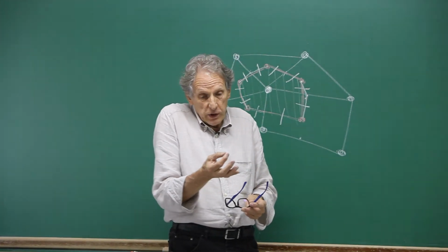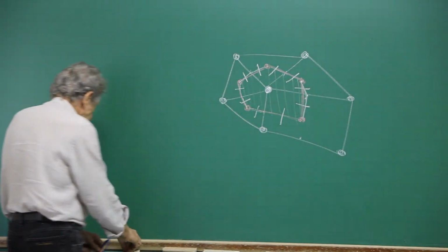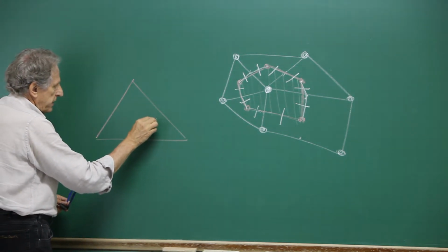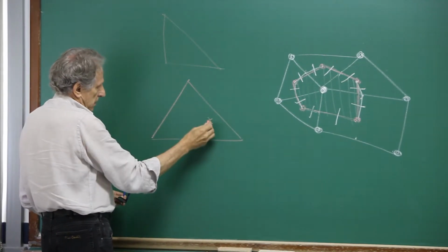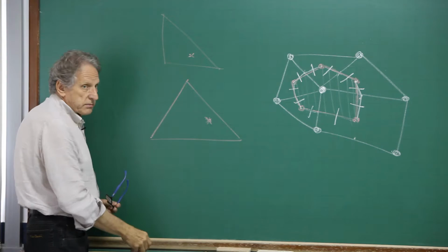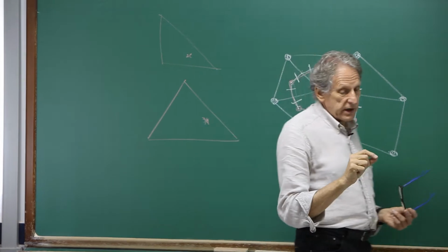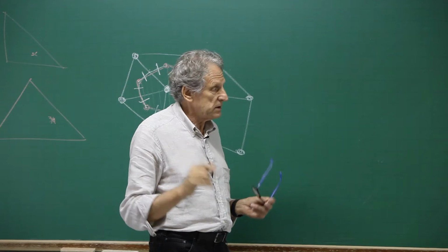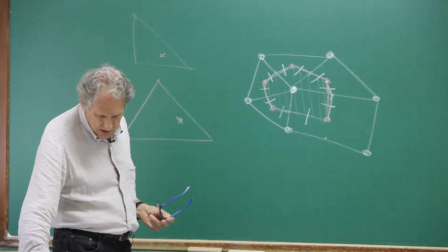If you calculate somewhere in the middle of the element, if you are calculating here, you have your transformation here, then you have some related point there. You can calculate at the vertex, in the center, at any point of the element. So it's very nice that you use the shape functions for that.